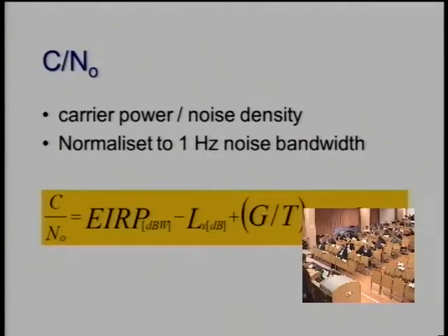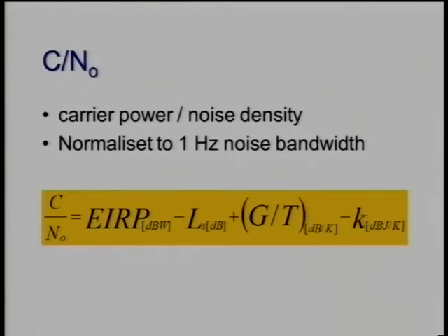Sometimes you find this figure, signal power versus noise density. Again, mathematicians wouldn't like that very much because this is power and this is energy. So I'm comparing 2 things, but in the end you will always calculate the dimensionless signal to noise ratio. Basically, this is just normalized to 1 Hertz noise bandwidth.